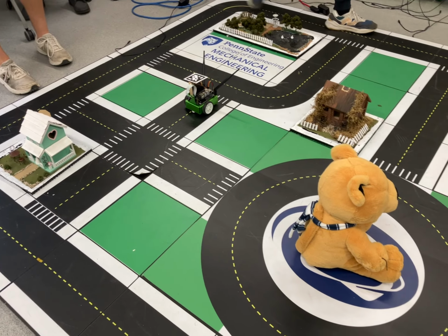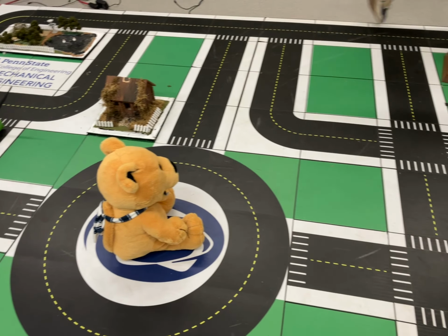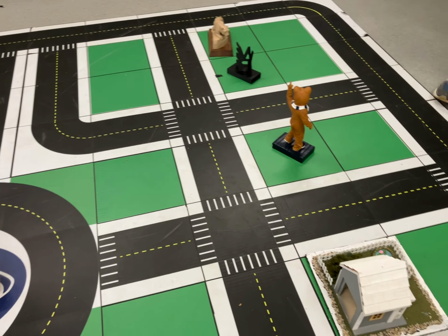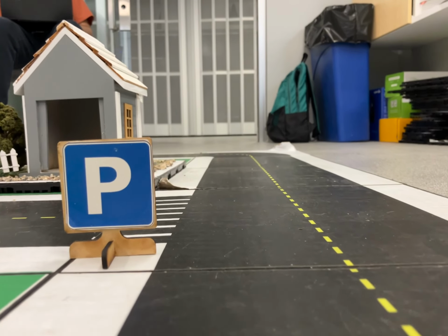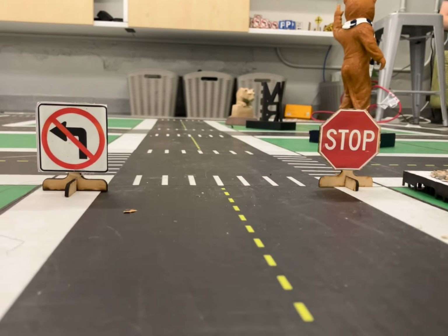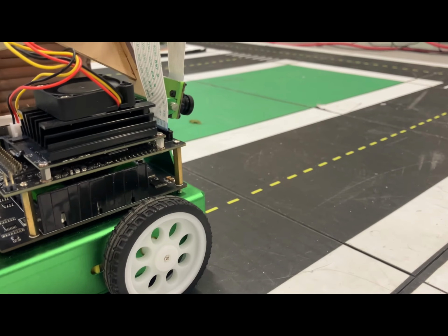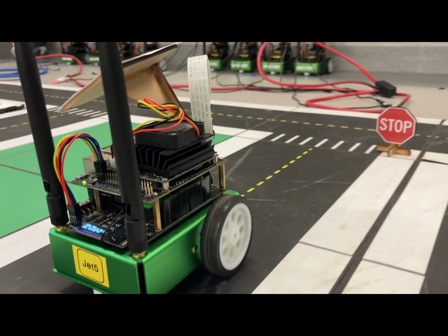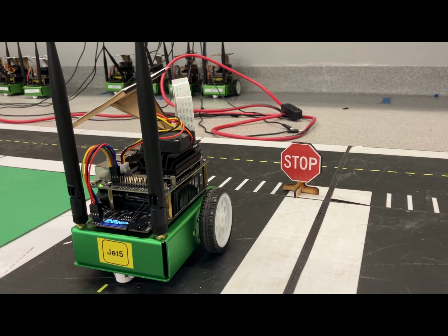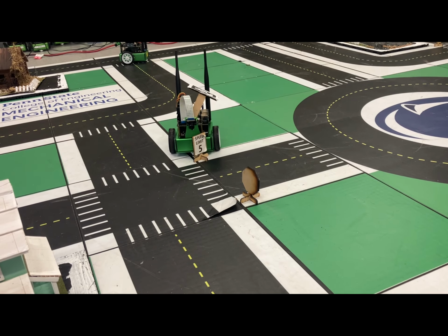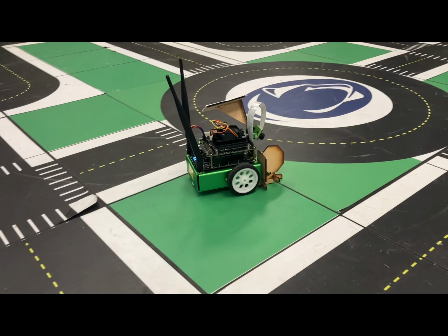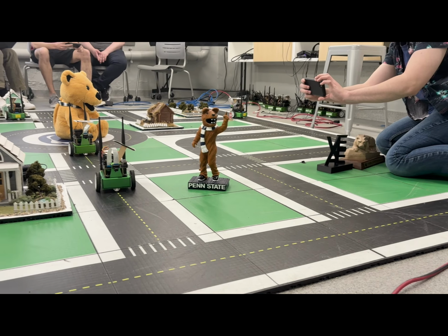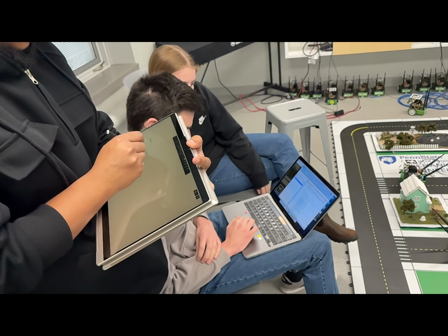Also in the second laboratory session, the team trained a model that allows the robot to determine whether a stop sign, speed limit sign, or no sign is present. To create our model, we took 30 pictures from each category, 90 total pictures. After taking these pictures, we trained and tested our model and found that it could easily identify stop signs and speed limit signs, but struggled to tell if there was no sign or a stop sign. To increase the robustness of our model, we used a total of 120 images that had no sign. After adding these images, the robot can reliably predict whether or not there is a sign.